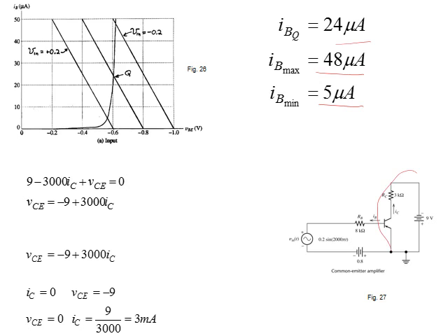For the collector, you see the voltage is in the reverse direction, the current in the reverse direction. Also, if we look from this side, 9 volt minus the drop across this resistance plus V collector emitter, the voltage here. And then we use the information given for R and the voltage to find the 2 points. When IC is 0, we find V collector emitter. When V collector emitter is 0, we find I collector.